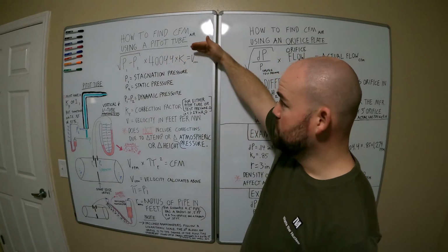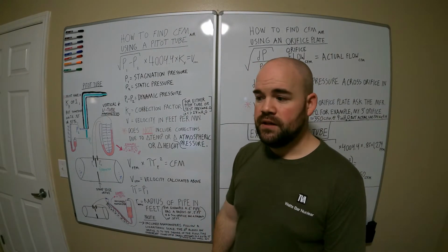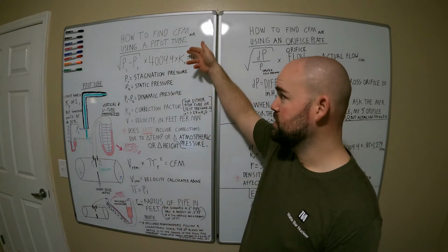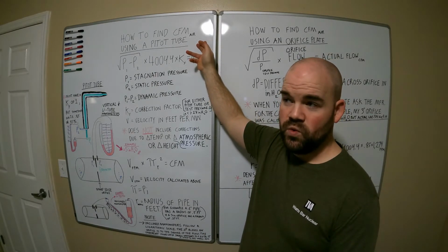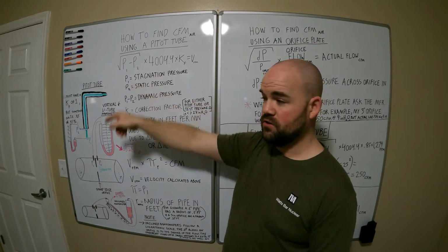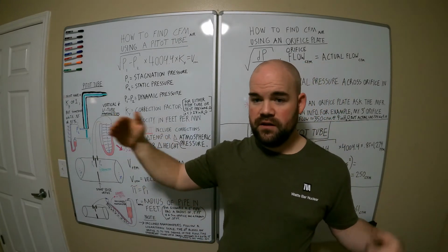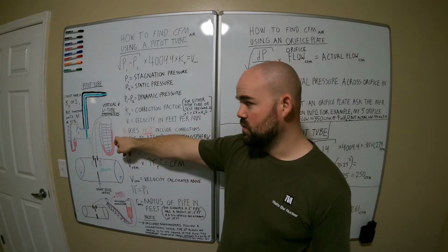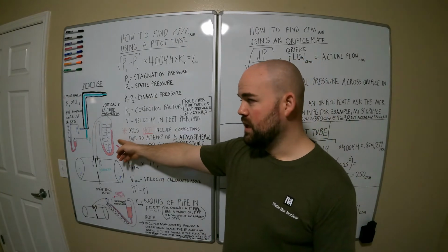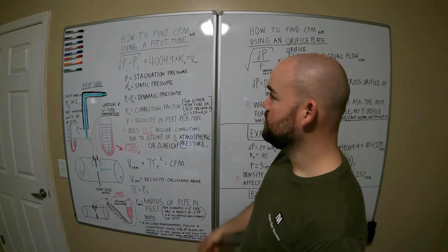Because, for example, a cylinder head that flows 260 CFM at 28 inches of water, then you're probably only going to see something like 0.1, 0.11, 0.12, 0.13 differential pressure across the tips from your static and your total flow. So you're going to want that scale to be very large and only slightly rise. And if you're using a U-tube manometer, it's going to be really hard to see that change. So just remember that you can do it, but your accuracy is going to go down the smaller you make your scale. Okay, so moving on.